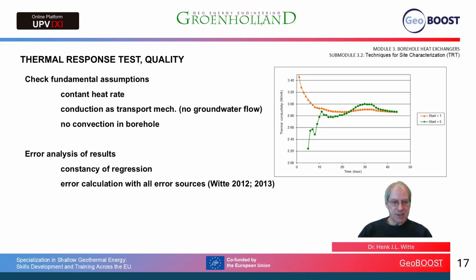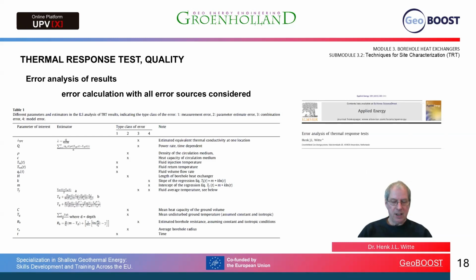An error analysis can be carried out, looking at this constancy of regression, but also taking a look at the error calculation with all error sources included. Here is the reference and some idea of the different sources of error that we can take into account. For instance, the heat injection rate, but also the density of the fluid, the error on the temperature measurements, the measured height of the borehole, etc.